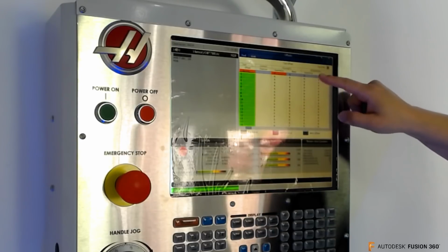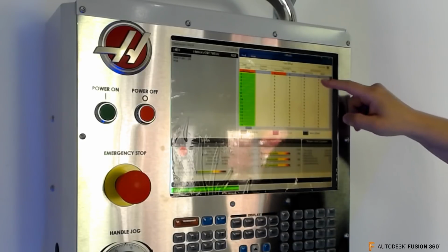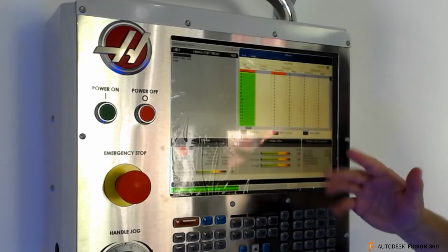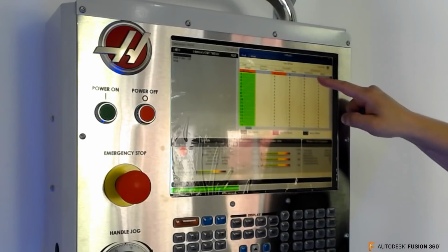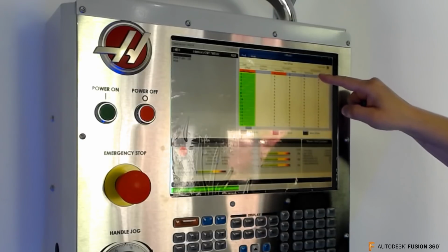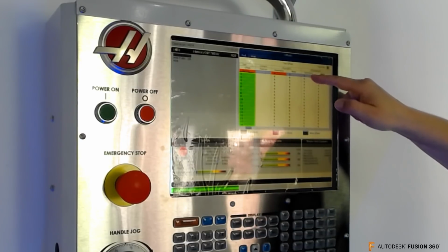The geometry is the full diameter. So if you're using in control, you will input the full diameter of your cutter. So in this case, the 10 millimeters. And if you have a probe on your machine, where it's measuring the diameter of the cutter, it will many times input that automatically there.